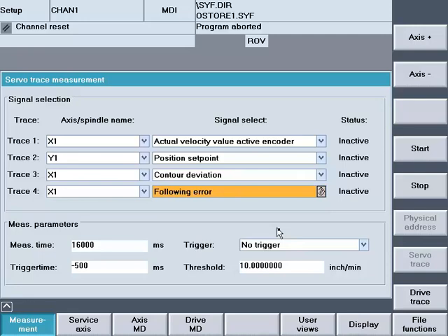What you can't do with contour deviation is assume that the value it gives you on the plot is absolutely correct. Sometimes it will be, sometimes it won't. It's kind of not worth learning when it is and isn't, because the way you use it is to validate: did something I changed make a difference?